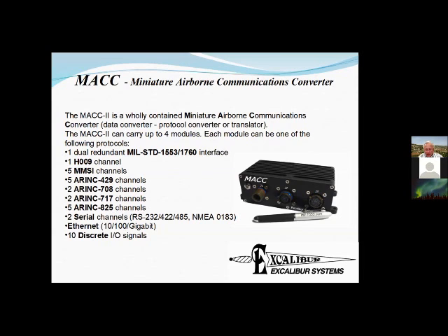So this obviously is much more complex than 429 to 429 because it's completely different protocols. The hardware is different. What defines a bit as a 0 or a 1 is different. The frequencies might be different. One of them might use gallons and the other one uses liters, or tenths of a kilometer and half of a mile. All of these are things that the Mac can handle, and neither side will be aware that it's actually talking to a device that has no concept of its language.